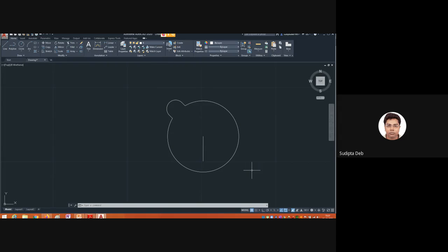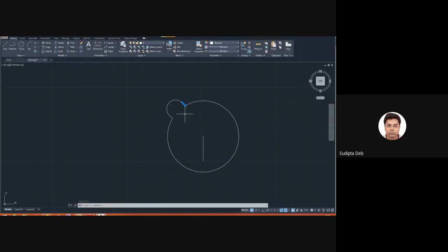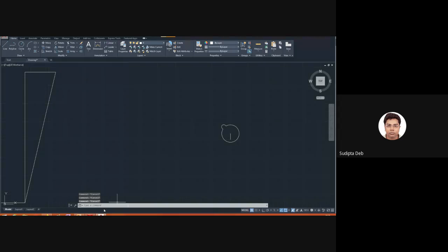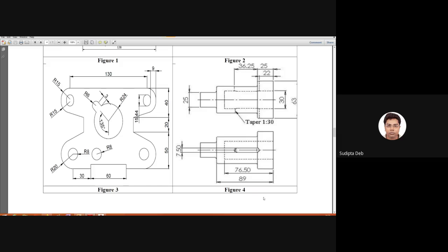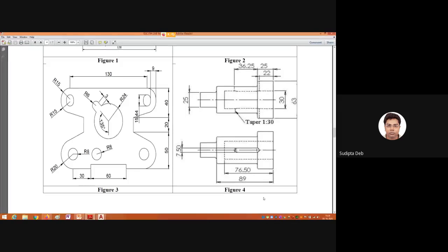So in this way we can draw, because there is some critical portion, because it is a circular section. This line distance is given as 3 actually, but if I take the offset, it will not touch. We have used the extent to specify the point on the circle. Then we have drawn the line and deleted the previous one. In this way we have solved the problem. So when you draw different diagrams, you can easily solve that type of silly problem.